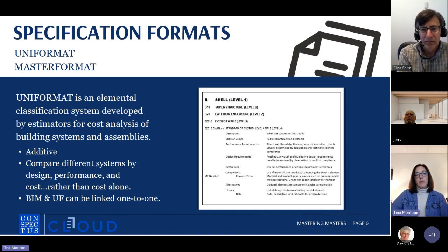And the BIM families are also identified in a similar system as Uniformat, correct? Right. So Revit does use assembly codes inside its libraries, and those assembly codes actually are Uniformat codes. So if you're working in Revit, you can organize your project using Uniformat.